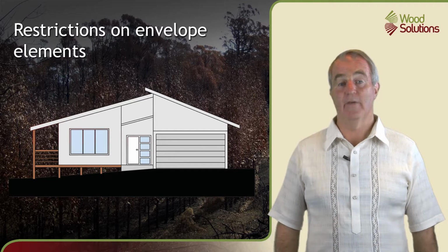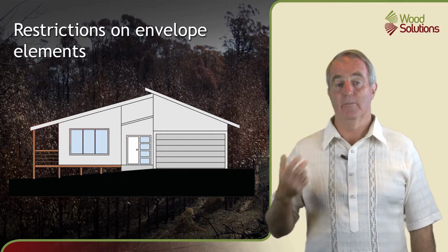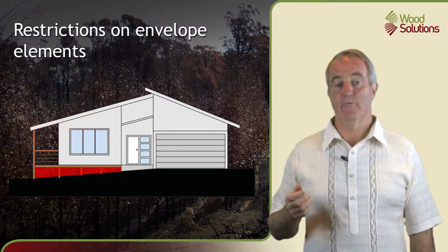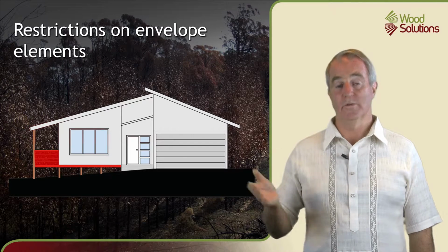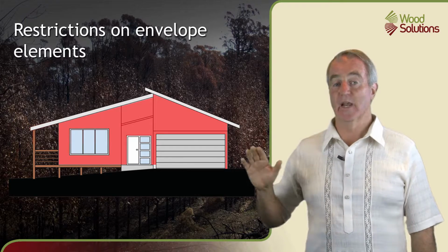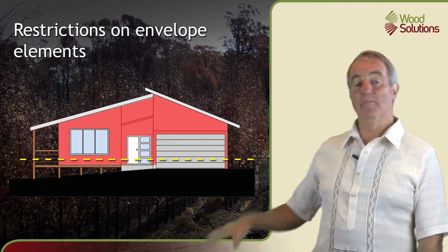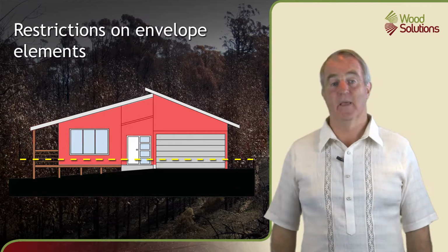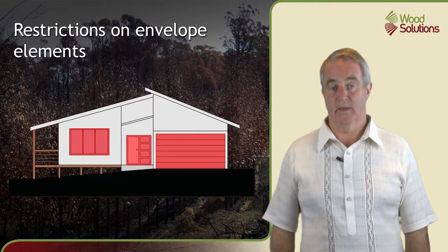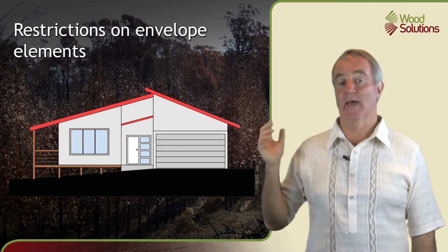External elements that may have material and construction restrictions on them under the standard include building subfloors that are either open or enclosed, stair decks and ramps, and external wall surfaces. These have separate provisions for surfaces that are less than 400 millimetres above an external surface and those that are above this 400 millimetre line. Also included are external windows and doors, including the glazing, window frames and any fire shutters, and areas in the roof, including the roof surface, the soffits, the eaves, the fascias and the gutters.